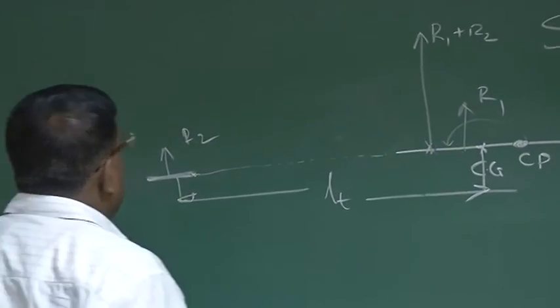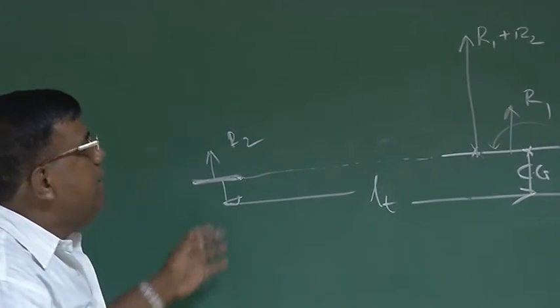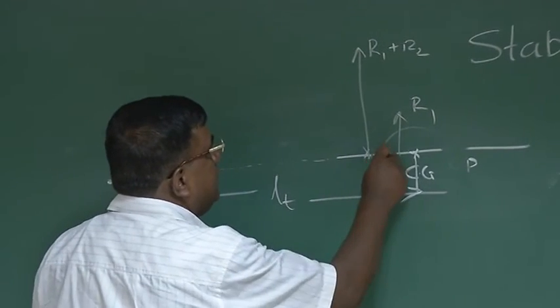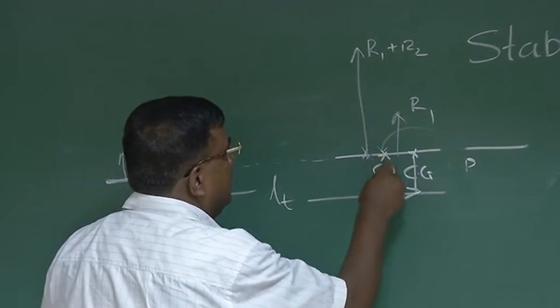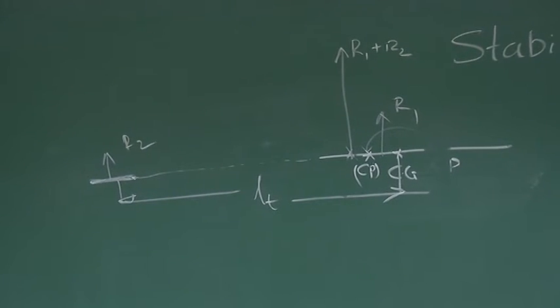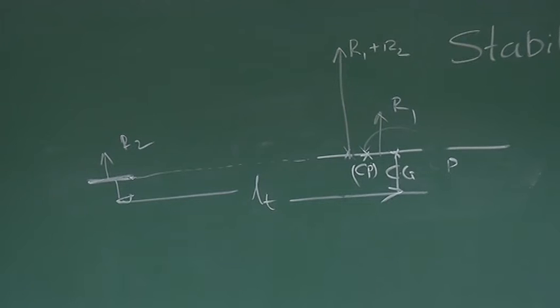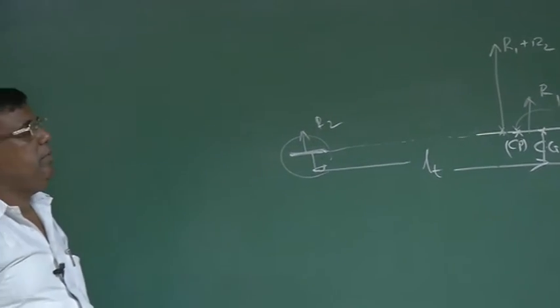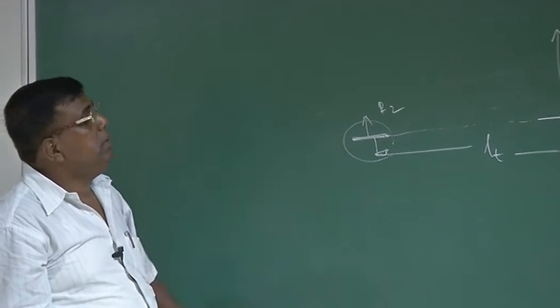And we also realize that once I do like this, then I can write that overall center of pressure, let's say, has come backward. So it is statically stable. So our one problem that I want to make it statically stable is handled through another plate here, small area, but at a longer distance from the center of gravity of the whole system.